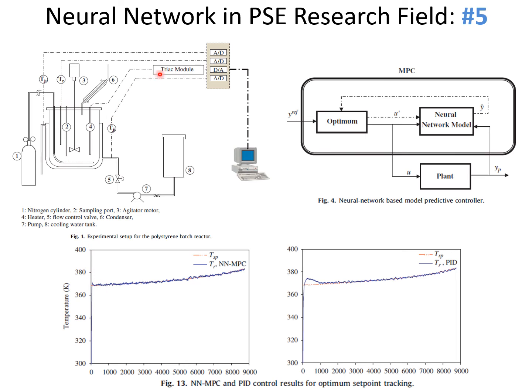The temperature is not coming just steady like that. It's going to be a little bit noisy due to sensor measurement noise, system noise, and so on. Many effects of noise, which are real world. But the neural network will be able to track it nicely within its profile. This has been trained offline. It's not online. It's been trained offline, implemented online with noise, but it's still able to track the profile nicely using the neural network model predictive method.